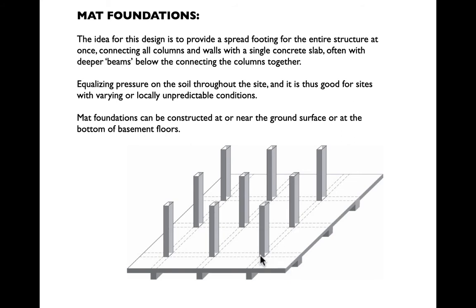So mat foundations are often quite deep to resist this, or they have to come with basically a grid of beams on the top or bottom of them. And again, that helps spread the shear out, but it also gives the mat some considerable strength in bending. And again, note in more than one direction, right? This is a two-way slab. It's just the load path is reversed. We're going from point load to a distributed load in two directions.